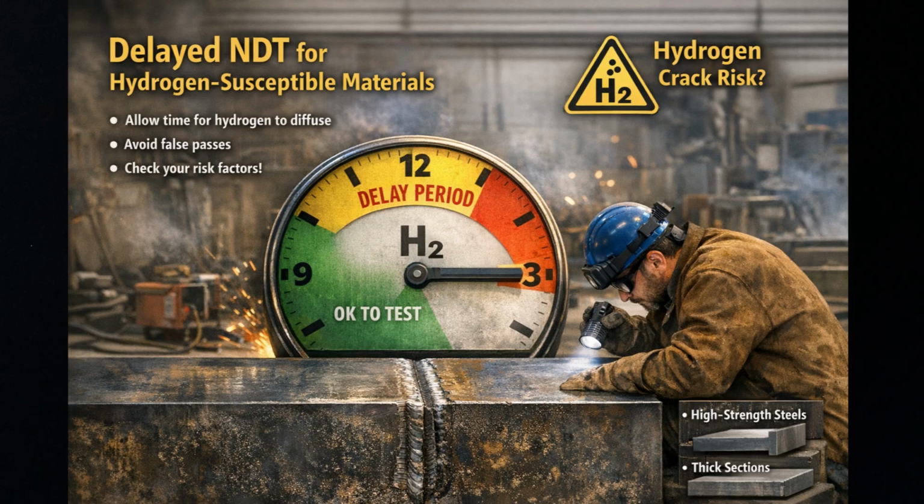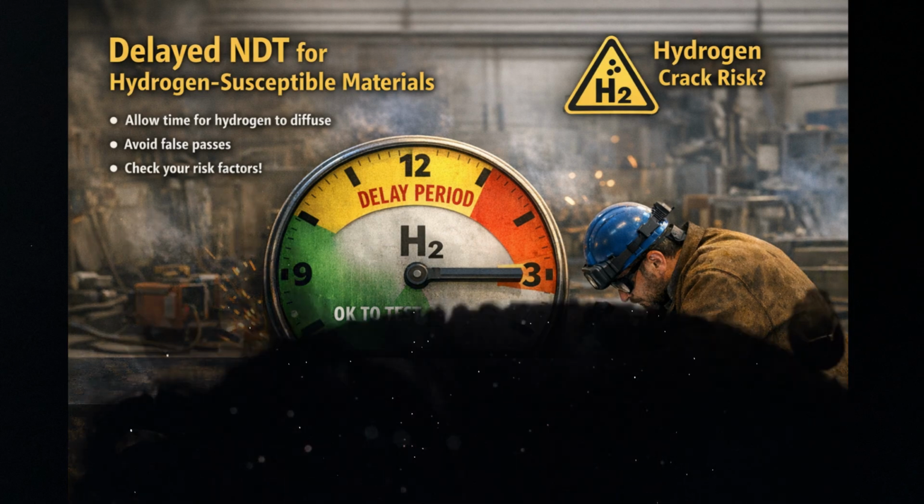The delayed NDT rule for hydrogen-susceptible materials is frequently overlooked. Always check whether your parent material and joint conditions put you in this category. Low alloy high-strength steels and thick sections are the main risk groups.